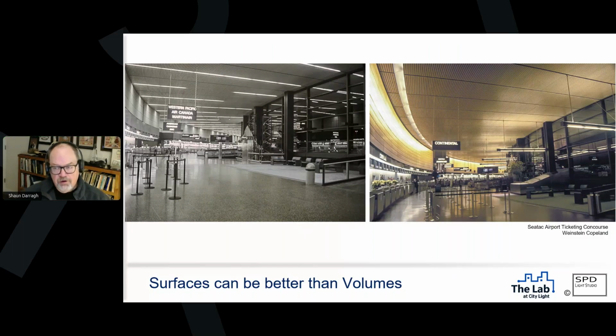Now, from an energy standpoint, we actually saved about 60% of the energy within this space. Still fluorescent, a different flavor of fluorescent to be sure, but I mean, we're still talking about fluorescent. We're not even going to LED at this point, right? So think about that. We've come up with a space that feels better, looks better, feels brighter to us than the old space did, and yet is using 60% less energy. And the actual measured light level on the floor, which we're all taught to look at in foot candles, is a fraction of what it was on the left, right?